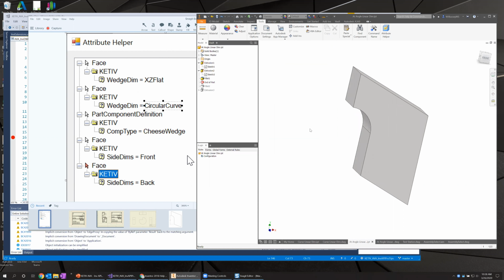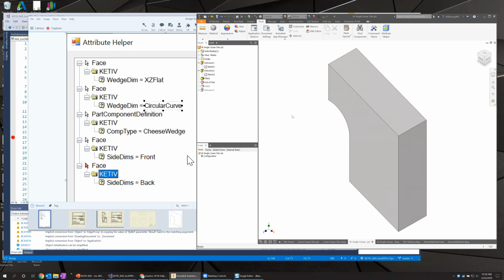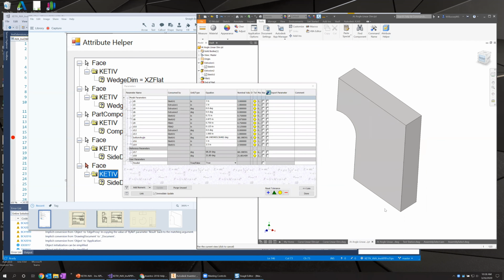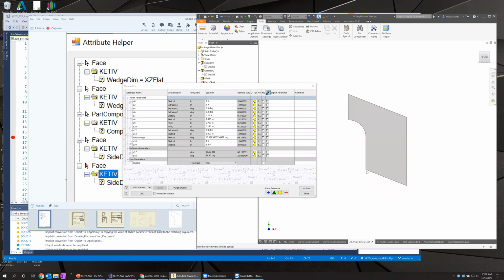Now, one of the things I want to show you before we get started, there's a reason I did this and it'll become more clear as we actually get into the automation, but this wedge has the ability, let me go to the front face here, where this bottom face may be angled this way or it may be angled down. You'll see this as soon as I run it. I've got a little iLogic code in there. So part of the reason that I have to use this face right here to figure out my length of cut is that this bottom face will appear and disappear, and the actual cut that I want to dimension in terms of its height may or may not intersect with this bottom face. So I don't want to use this bottom face because it'll be in a different position and may not be part of the dimension I want to create.